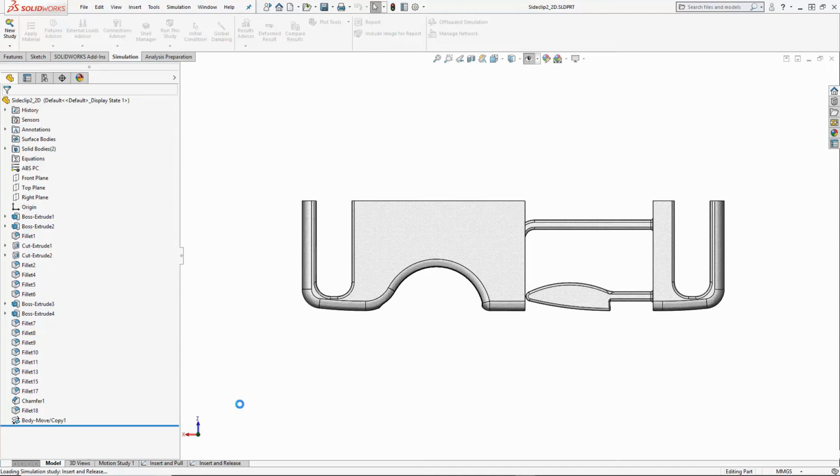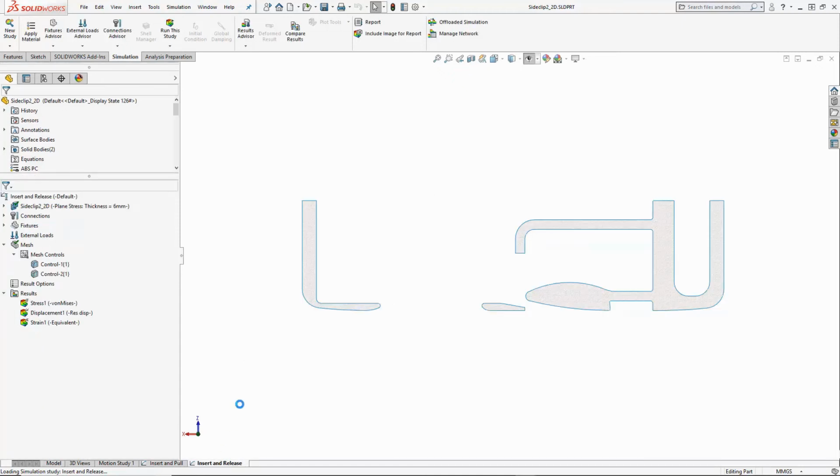Another nice thing to go Sim Pro or Sim Premium is that you can break things down to 2D. In this case, I have some good symmetric assumptions, so I actually set up a 2-dimensional nonlinear study here because it's going to solve much faster. I really haven't changed things in the materials too much, just used a plastic. And again here, I haven't applied any external loads. In this case, I decided to just be slick again and just use fixtures.